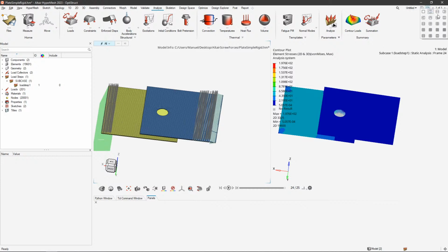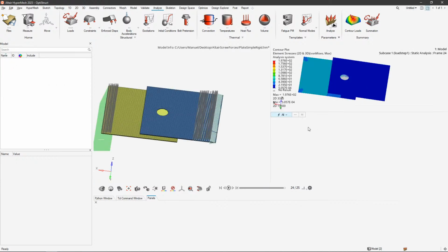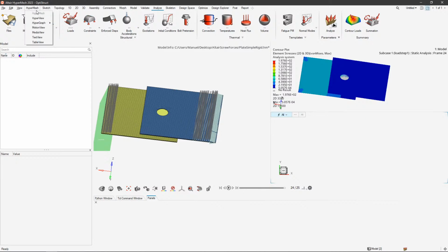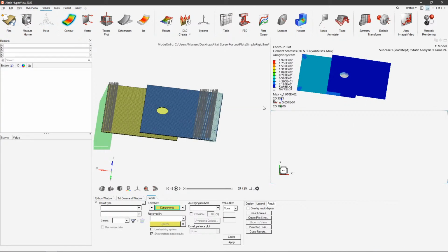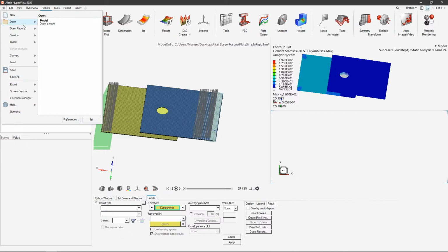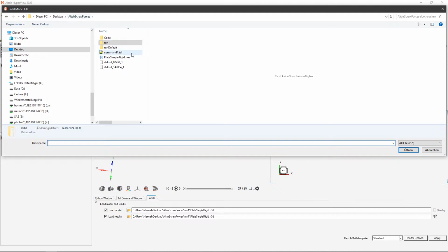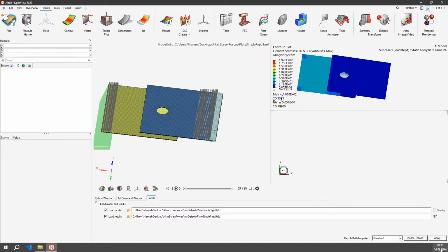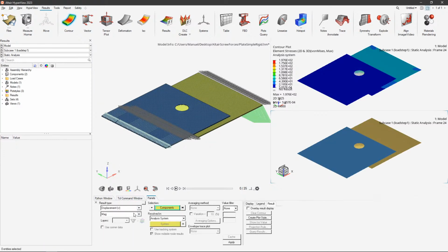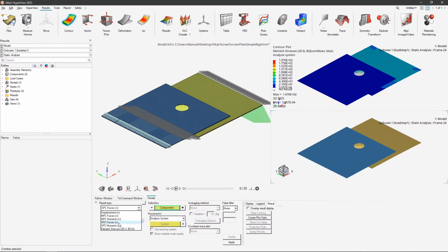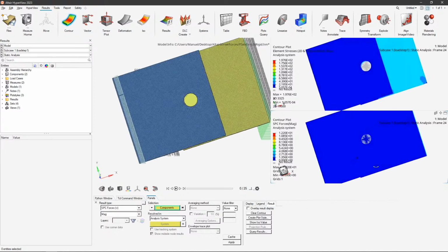Let's just get another view here. I could specify it also as H3D, but I think the default case is H3D. Sorry, that's still Hypermesh. So run, no, not command, run default. So if I open the H3D file here, I would suspect something like SPCF or MPC forces. Yeah. So you have SPC forces here in the H3D file, right?